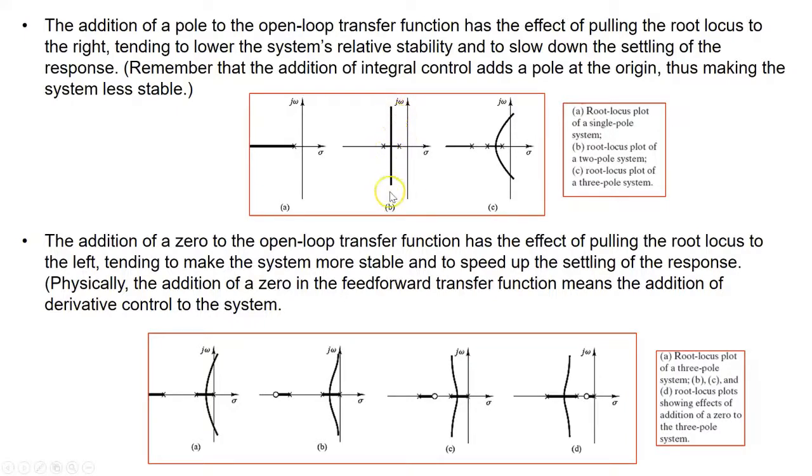Now, if I add one more pole, the root locus is now quite vertical. It has these two portions, small ones as well. So after a little bit of real roots, now I'm kicking into what? Imaginary roots. And these imaginary roots have a negative real part. So what kind of behavior is this? Yes, that is underdamped, right? So unless the roots are on these small portions, the rest of it is underdamped behavior.